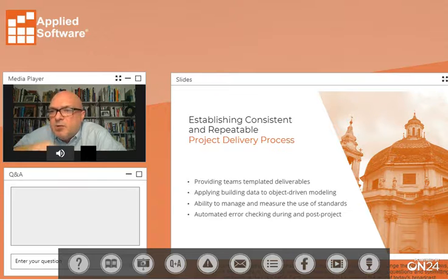The warning system in Revit, right? It tells you, okay, here's how many errors I have. Well, those things are passive. They're not meant to stop you from doing things. They pop up and they keep a running log. But if I analyze those and use those, and then make some countermeasures that steer people in the right direction, then I might have fewer issues. Because often a lot of those errors are related to inconsistencies that you've introduced in the project, frankly, because of human error. But also, if you don't plan to have something be repeatable or consistent, then that's also an error, right? The lack of doing something is also going to hurt the project.